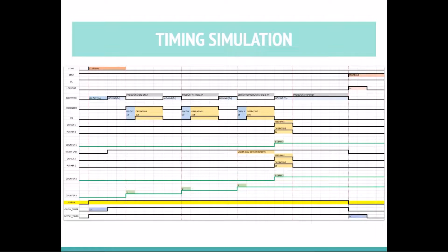If any defect is detected at the jig, it will give feedback to the pusher and it will push the product into the NG box while the conveyor is running. The inspection process will run for 11 seconds, including the 1 second delay after the sensor detects that the product has arrived, and 10 seconds for the actual inspection.